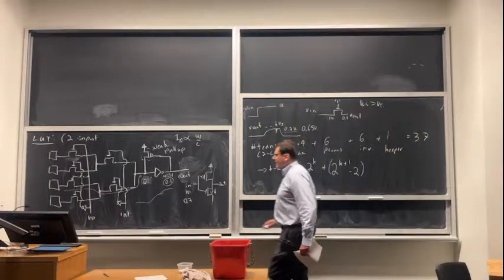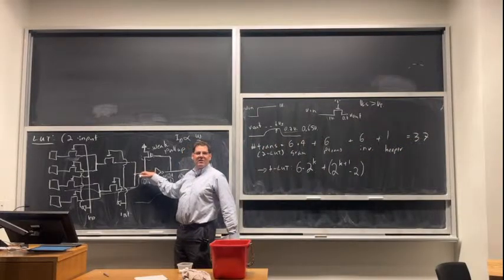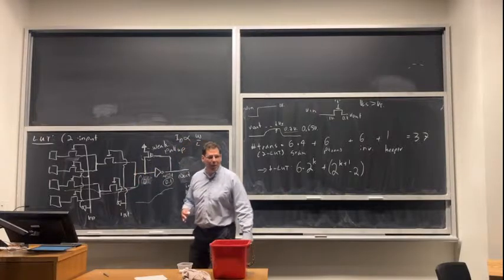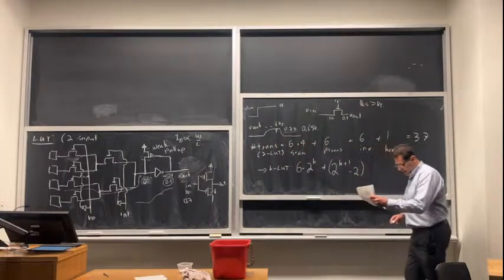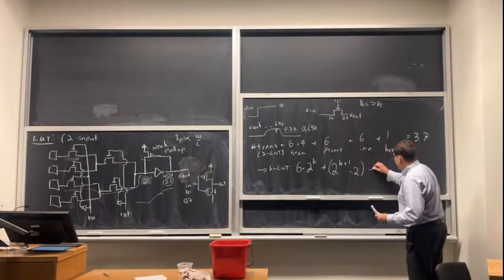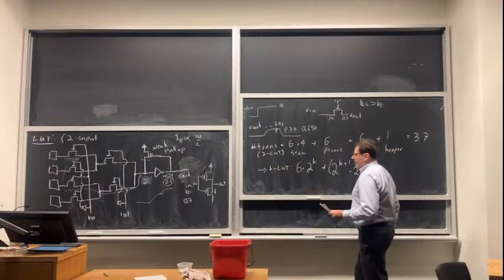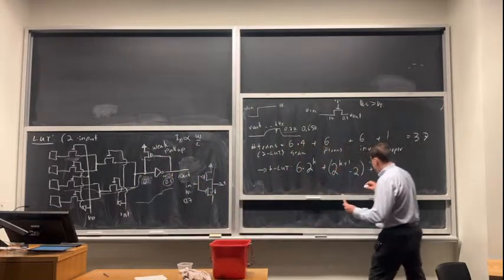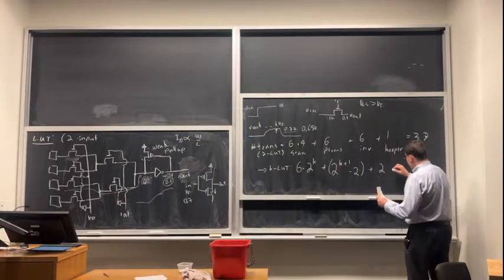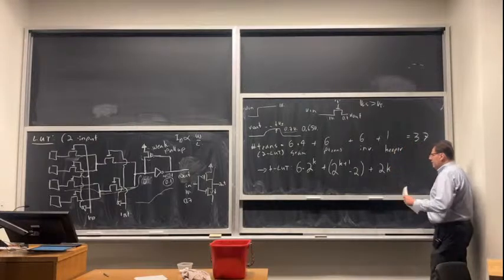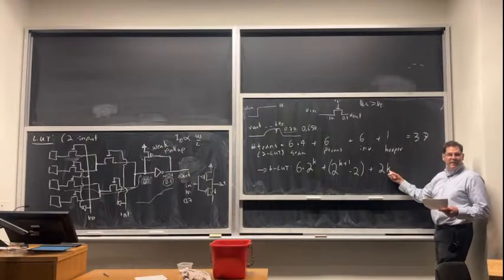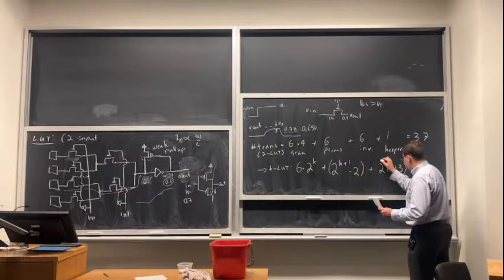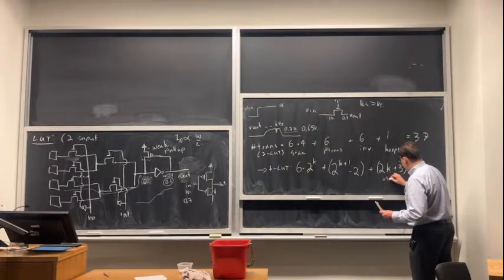But the last stage would be just a single pass transistor that's always on, which there is no purpose in doing that. So you take that out and replace it by a wire. That's where you get the minus 2. Okay? And then the number of inverters, I need 1 for every input plus 1 for the output. So generalizing that is pretty easy. So it's 2 transistors per inverter. I need K of them, plus 1 more, plus a keeper. So 2K plus 3. Okay, and that's basically inverters plus keeper.